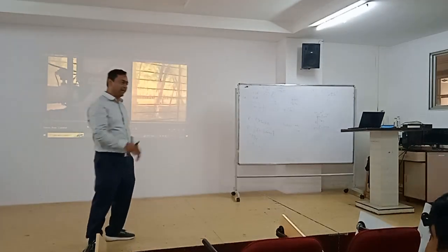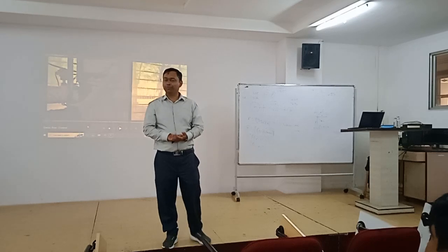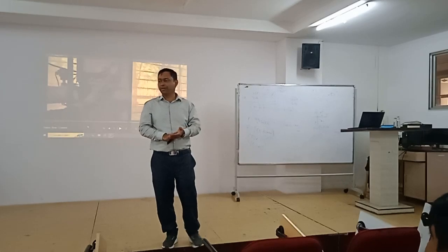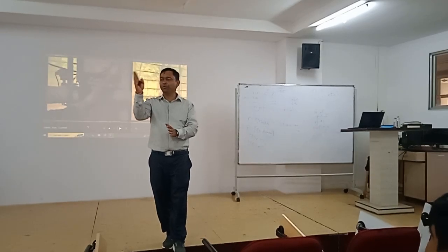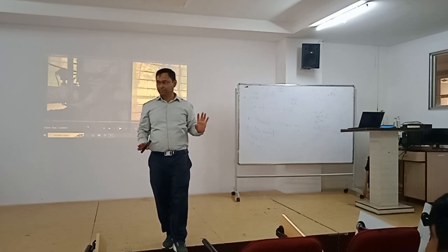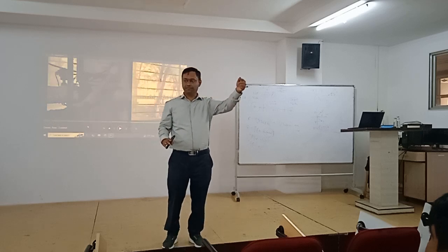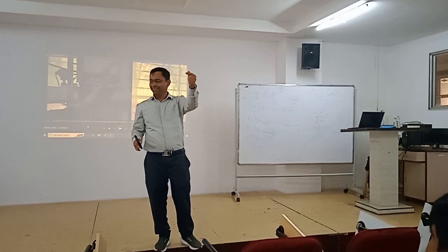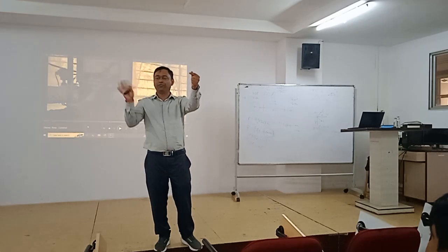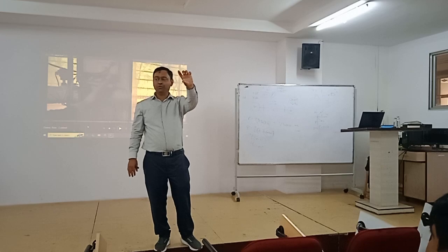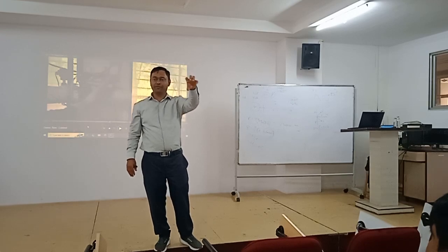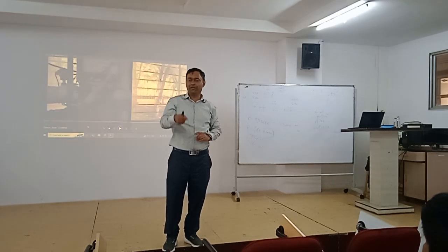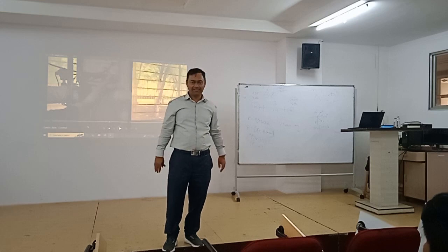See, now here what happened? Again, go back. Your system is working in closed loop. The purpose of the control system was what? To maintain the output same as the desired value of input. Have you changed the desired value of input? No, it's 50 only. But you make the actual value of flow 0. So there will be a huge error for the controller. So it will be in action and try to nullify that difference.